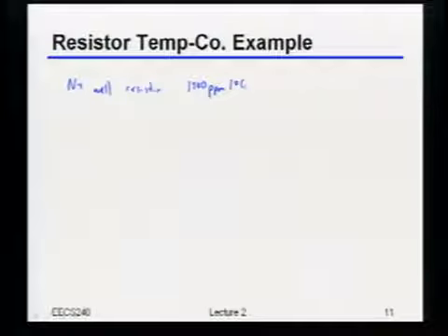Okay, so if that's how big my temperature coefficient is, by the way, ppm just stands for parts per million. So that's just like 1e minus 6, basically. And it's a relative variation. So it means something like, well, I don't want to do the math in my head, but something like 0.0015% per degree C. Okay? So what would be a standard temperature range for you to deal with in ICs?